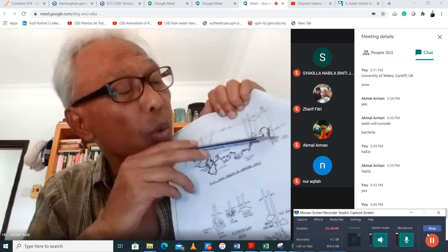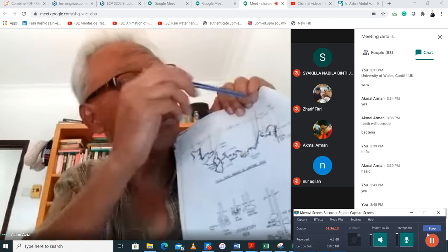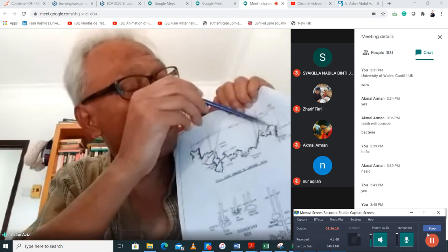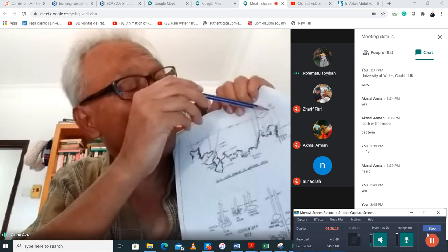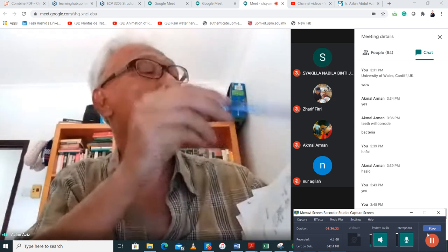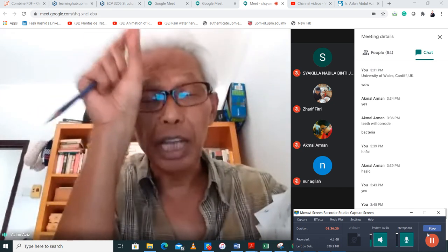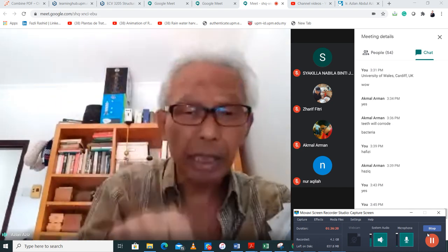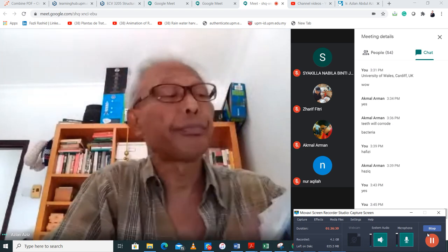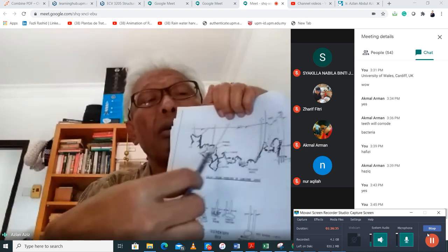And then you bond it, you put glue onto it, and then you excavate a hole, and you put reinforcement. Then you pour your concrete, your bored pile. So you have your bored pile being attached to a micro pile, being bonded to the solid rock. All right, that's the solution. Otherwise, you get all this problem.